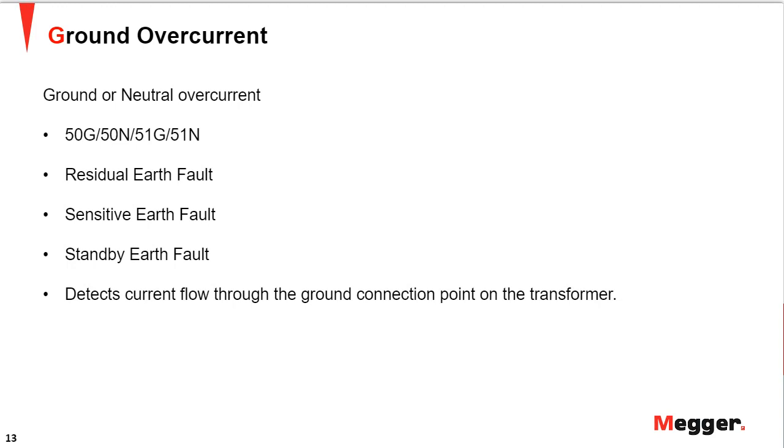So we know that a residual current will exist if there is an imbalance, a fault in the system that flows to the earth. That's how you could obtain that fault current, and then the relay can decide based on a set point whether it's a ground fault or not, right? And these kinds of relays need to be time coordinated with the downstream relays for sure.